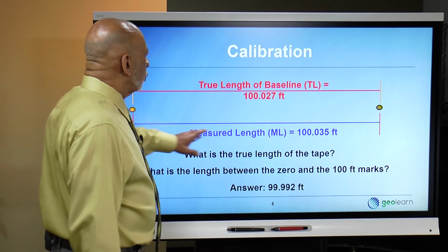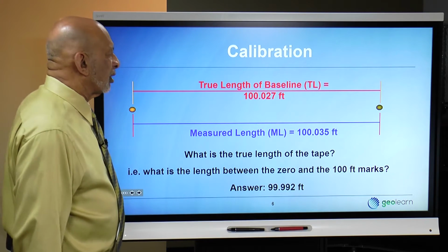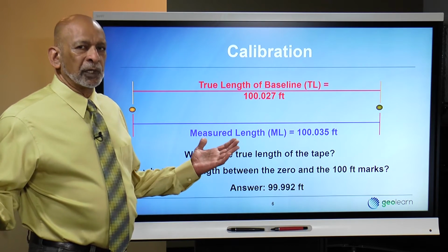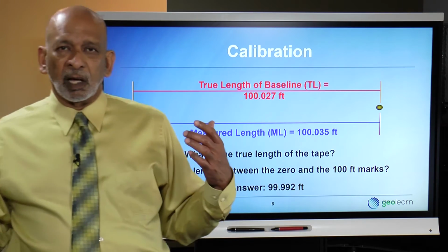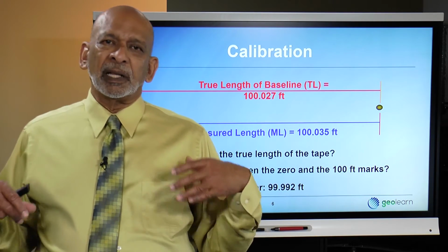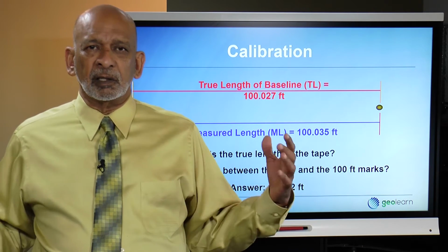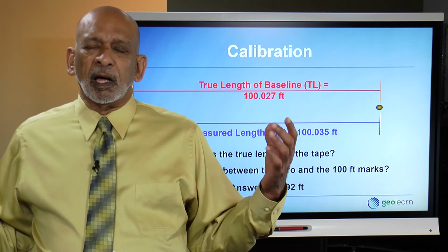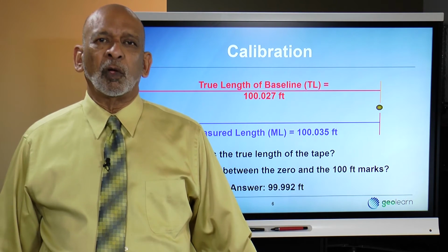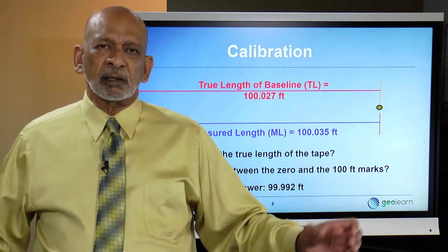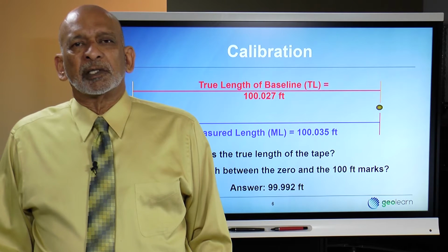We have two marks that are very precisely set. And usually what happens, we set 2 points. They might be brass discs set in concrete, on a sidewalk, on the floor of a building, in the pavement of a road, or if it's a dirt or grassy area, you would probably have cylinders of concrete that are several feet long that are embedded in the earth, and the brass discs would be on the top of them, because you want these to be very stable.